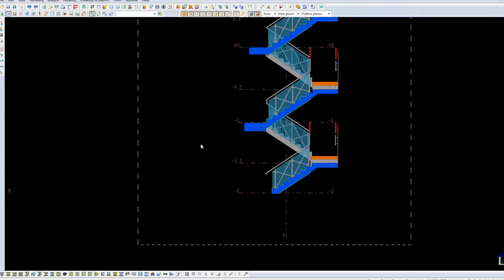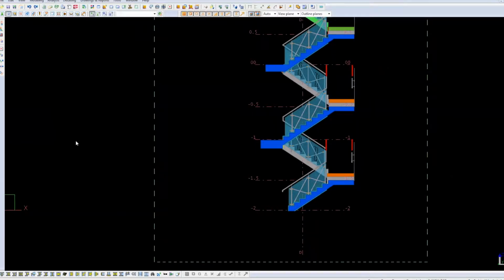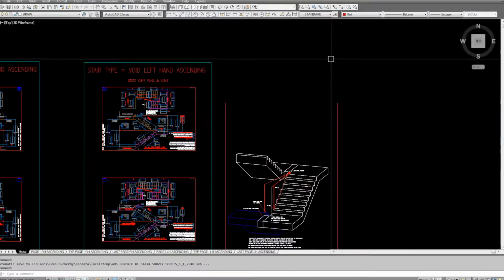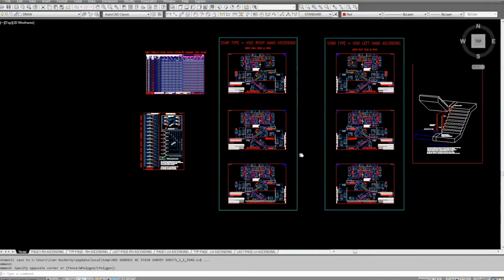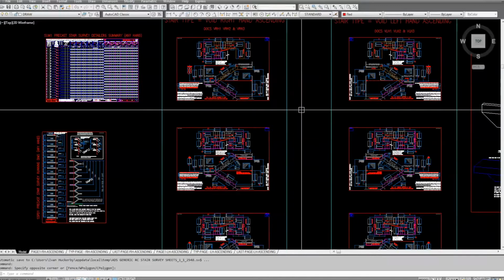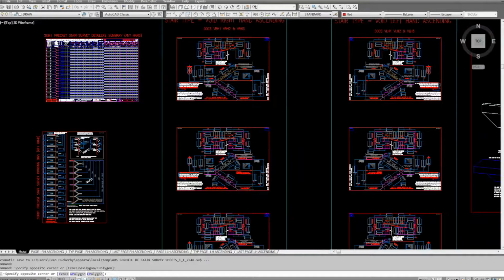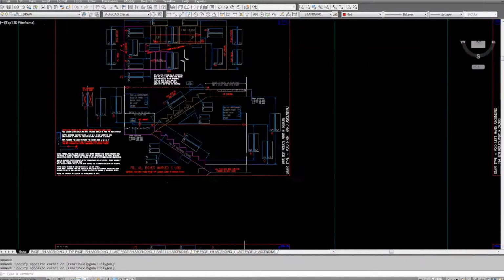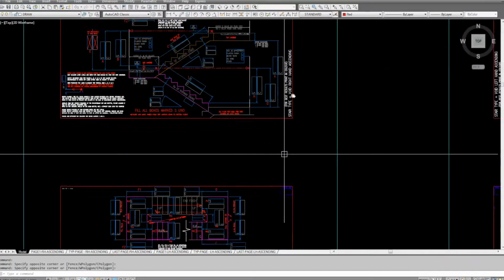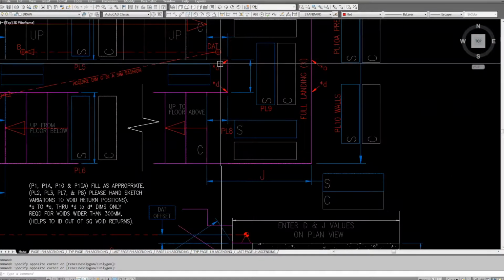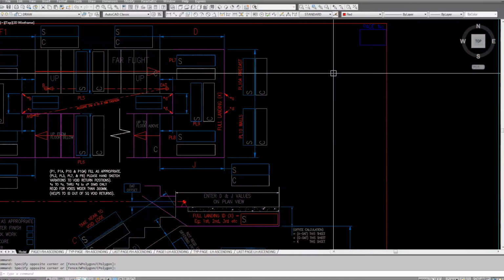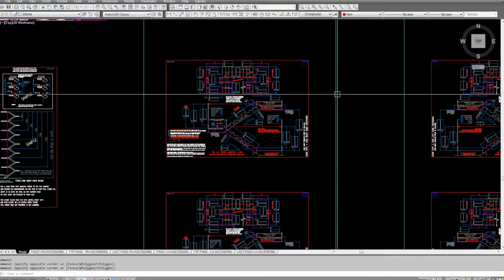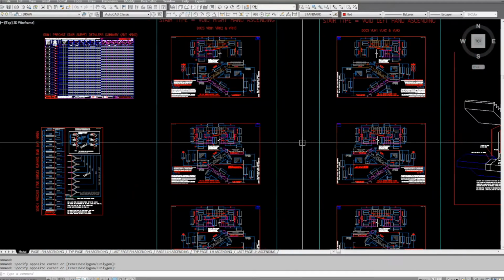I pre-drew the stairs out in pairs of flights, and that has developed over a couple of years into this document. Now, what I've got here is for a typical dogleg stair. You can adapt it a little bit for stairs with short little infill returns. You can have wide voids, that's upper landing. So if you've got a couple of treads or a couple of risers going in there, I just sketch them to one side. But generically, these cover most concrete stairs.